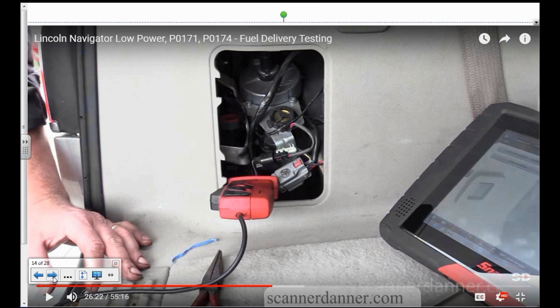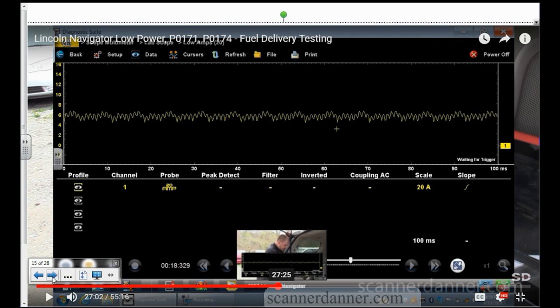Standard fuel pump troubleshooting involves using an amp clamp and checking my current flow, and I'll show you why as we continue here. I don't want to lay in the gravel on the ground. I want to know either at the relay or at the fuse, or in this case at the inertia switch, what my pump's doing. So we're taking some measurements. I do ask you guys this stuff on your exam coming up about fuel pump current and fuel pump RPM and speed. So pay attention. You're going to get these answers within this little case study review.